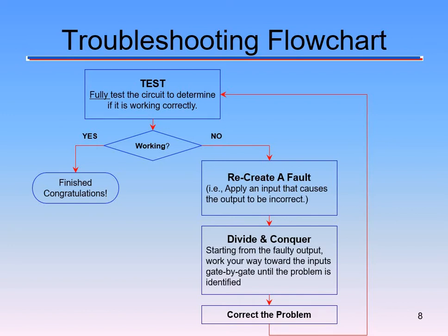So I want you to think about that. Put yourself in that error situation and take all of your readings as you go through that error. All right, where did you miss? Why are you expecting a 1? Why is it giving us a 0? All right, so there's a couple different things. Is the logic gate bad? Did I miswire something? All right, a couple. Just take different approaches. Oh, the wire's coming from the wrong location. It's not even coming on.